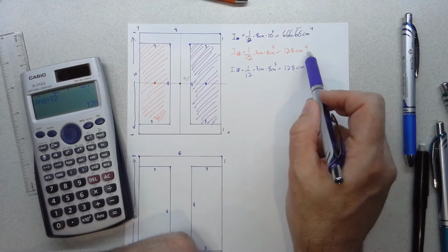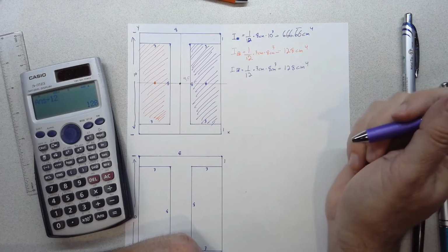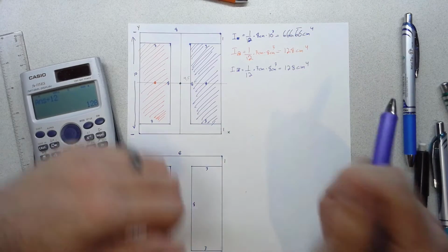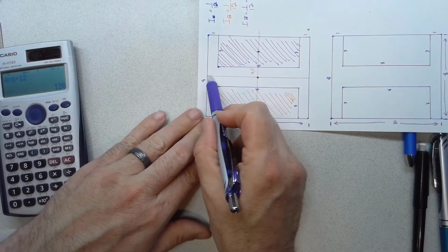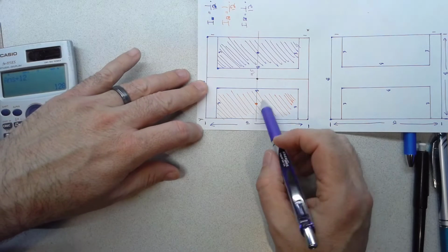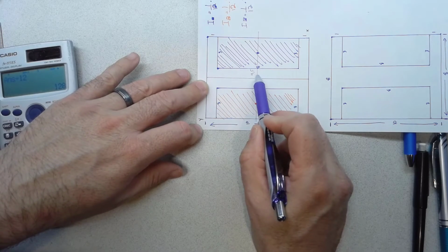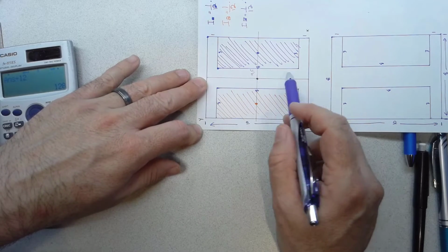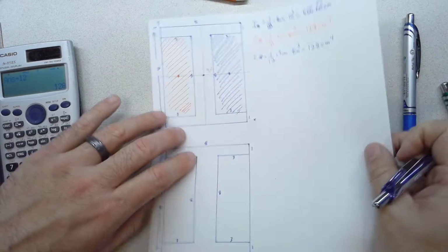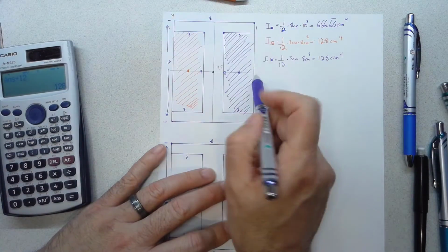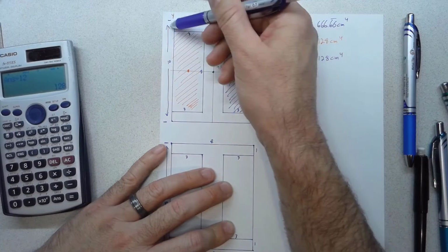Okay, so let's talk about that a little more. I did it twice. Really, it would have been just fine to find the component I of the orange part and then just multiply it times 2. It'd be the same thing. I just want to stop here for a minute and talk about, let's say rather than finding I about this axis parallel to the x, we were looking at bending along this axis of symmetry. In that case, you'll note that the centroidal point of the purple and the orange is not along the bending axis of the final shape. So in that case, I would have to use the parallel axis theorem. We'll look at that in the future, but I'm able to avoid using the parallel axis theorem when bending about this axis because the centroid of each of the pieces I'm looking at runs through the neutral axis of the whole composite shape.